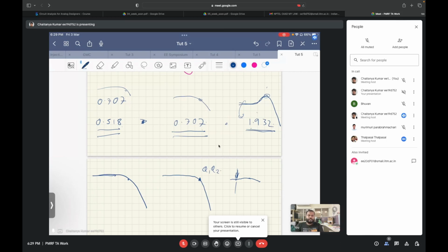Here, the problem in this is you are basically doing the dynamic range scaling pessimistically, because if you do it individually, you will see this peaking. But if you cascade these three biquads, this peaking will go away. So in that case, you would have to do lesser dynamic range scaling than what you did at this point of time. Are you getting this point? Yes, sir. Exactly.